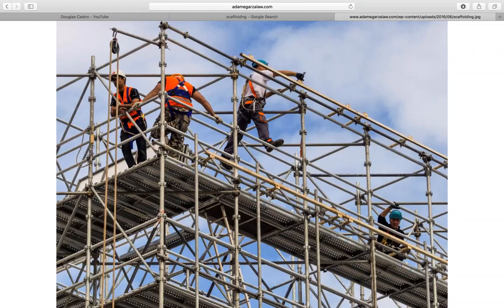Also, what can go wrong to release that energy? Is it something with stored energy, like springs or struts or shocks, right? Is it something that's locked out or tagged out? Is it like a dump truck bed that may be caught in the up position, or a press that may be caught in the up position, and gravity may bring it back down, right? Push it back down. Also, how can the energy be eliminated, or how can we control it?